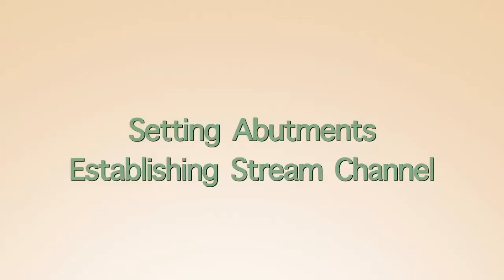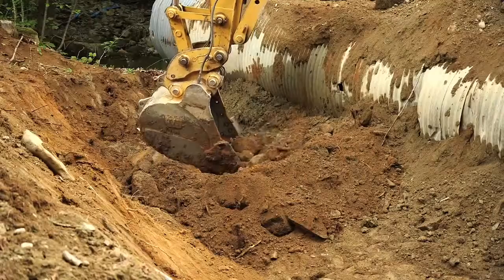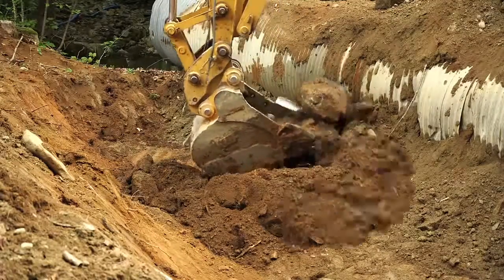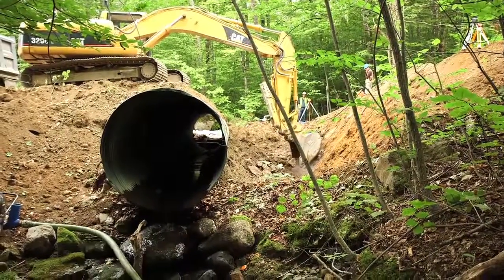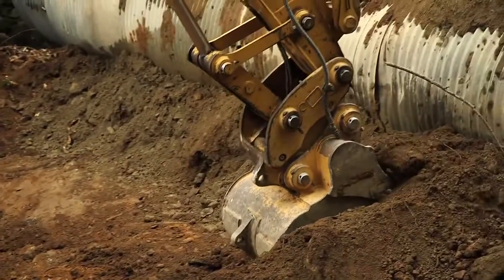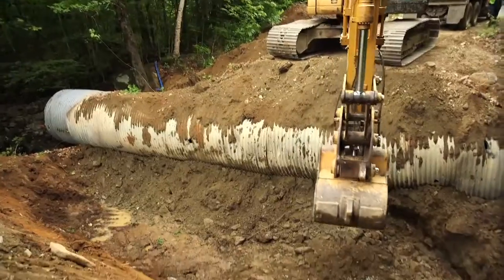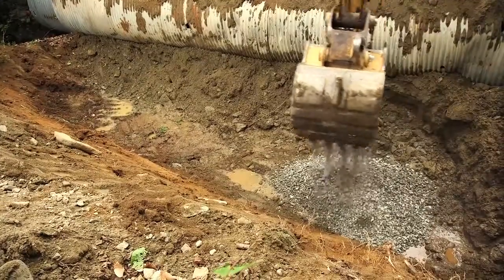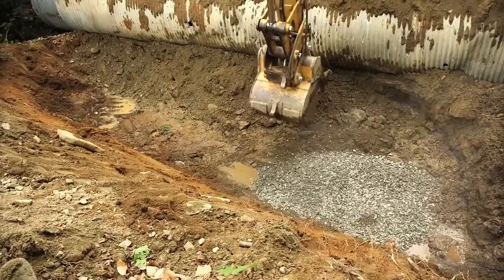Setting the abutments and establishing the stream channel. The excavation for the abutments is dug down to the bottom of the bedding required for the concrete block abutments. Typically, 6 inches of coarse gravel or crushed stone is placed under the abutments for the bedding material, so the excavation has to be dug at least 6 inches below the design elevations of the base of the abutment. Here they are excavating for placing the bedding material and then placement of the bedding material up to the elevation of the base of the abutment.